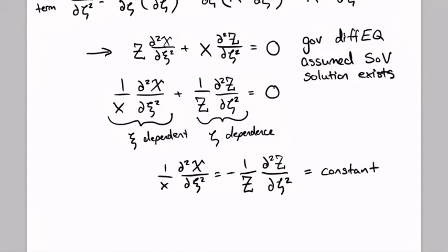And the obvious constant we think of is 0, but if both sides of the equation are 0, there is no temperature dependence, and so we're not actually solving a differential equation. That's mathematically correct, but that doesn't go very far to giving you a temperature profile through the slab. So basically, our separation of variables technique has given us two differential equations that we can solve. And that's exactly what we were aiming to do, to separate out the two equations so that we could more easily solve them. Because a second order linear homogeneous equation is much easier to solve than a second order nonlinear equation.